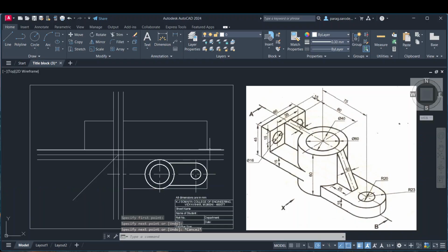One thing you can notice here is that ortho mode is not on, but the polar tracking mode is on, because of which, even without the intersection of this circle with this edge, we are able to draw the edges which are connected here. If ortho mode is on, then we might have to extend it, and then trim this part, right? So this is one advantage.